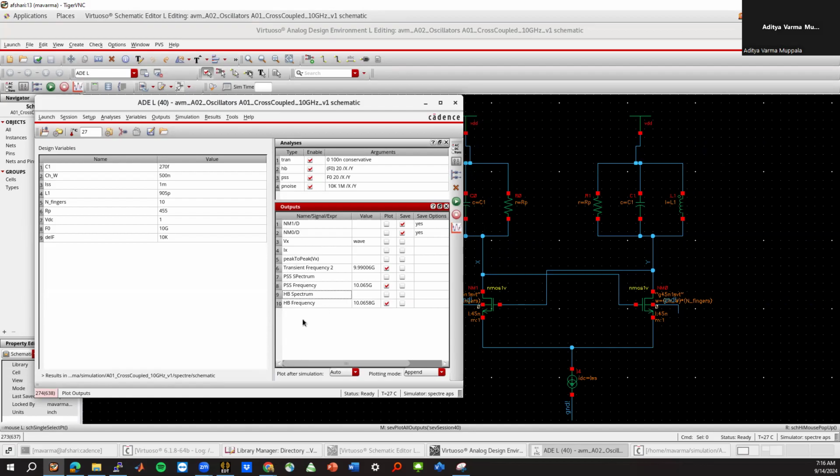So far we've looked at, I mean, power consumption is fixed already. We got the right swing, we got the right VDD. I mean, VDD is fixed, sorry. We got the right swing, we got the right current steering, and the current density looks fine. So even the first pass design was very accurate, right? So you can obviously tune this a little bit if you care by tuning the capacitance values. For example, if I make this 268 femto or 272 femto, maybe that would give me slightly better results.